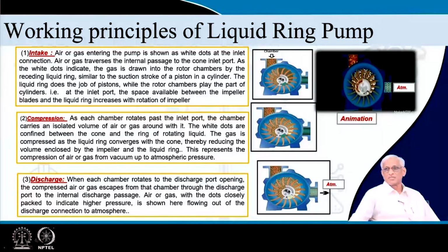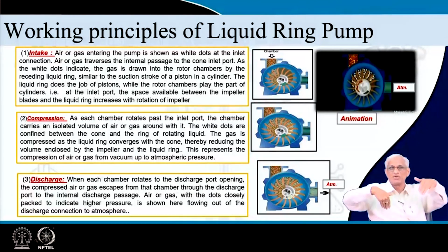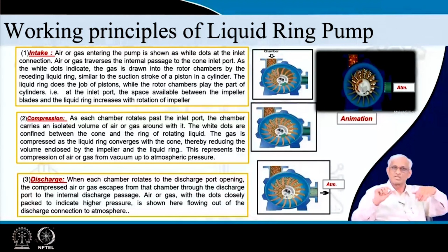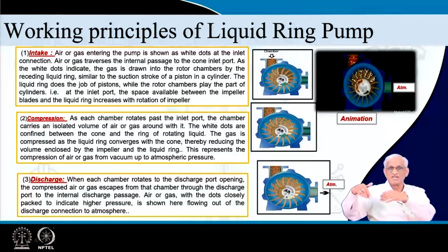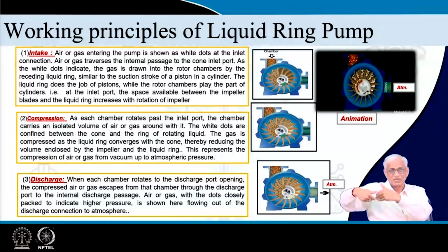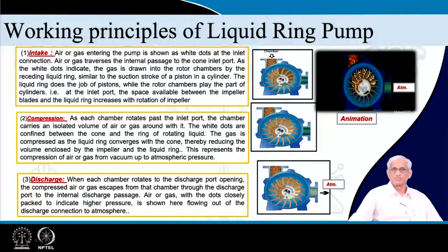At the end, pressure will be slightly more than atmospheric pressure, and it opens a spring loaded valve, so that it just pops off that gas in strokes. Okay. These valves are not permanently open valves, they are connected with some spring loading. Only when pressure is more than atmosphere, that valve opens. Similarly, in the suction side, when the pressure is less than atmosphere, the inlet valve opens. In both the conditions, there are certain spring loaded inlet and exhaust valves.